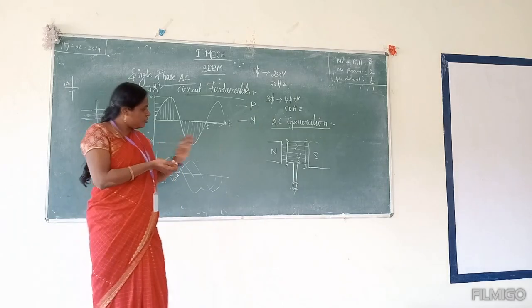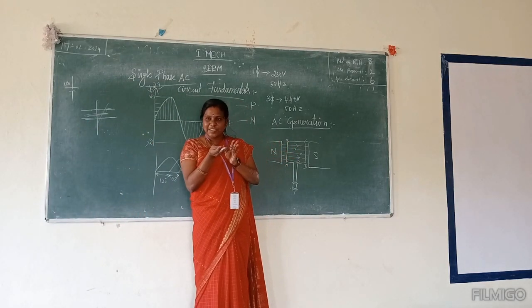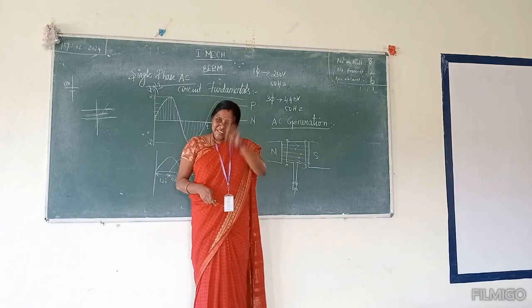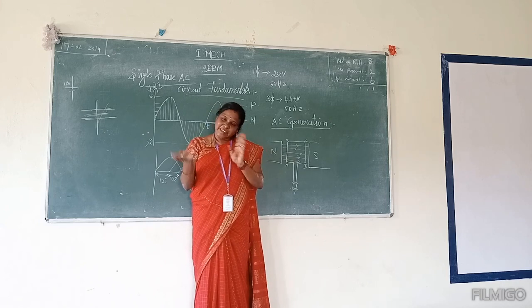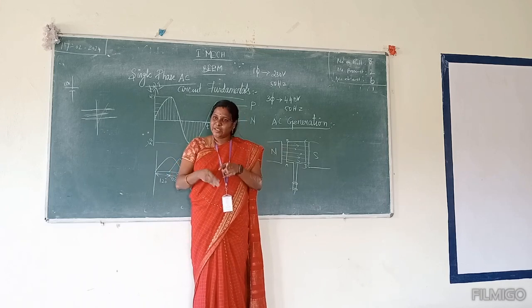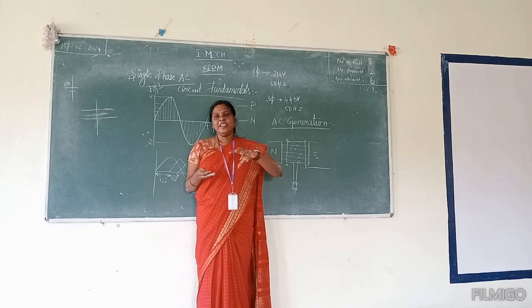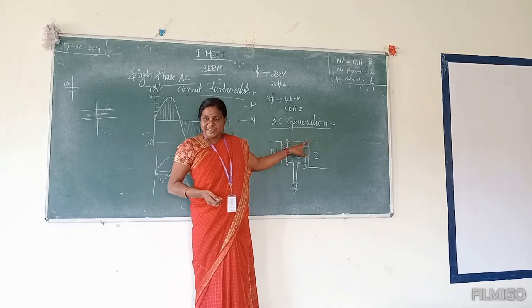Okay? So you understand? This coil will be parallel initially with respect to the flux lines. If I rotate the coil, it is perpendicular and cuts the flux lines. Then again I rotate, it becomes parallel. Again I rotate, it becomes perpendicular downward. So this keeps on happening. Which means EMF is induced when a coil cuts the flux lines.